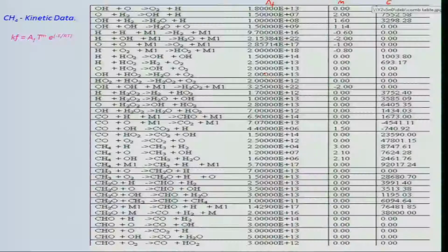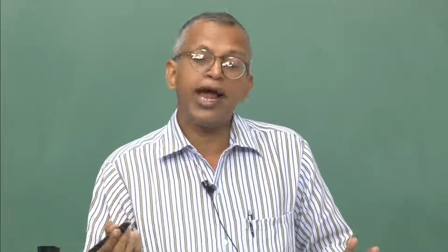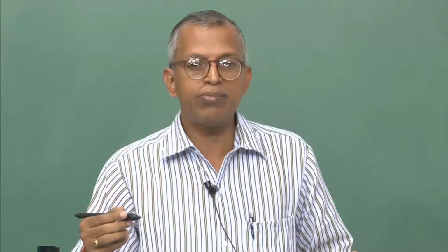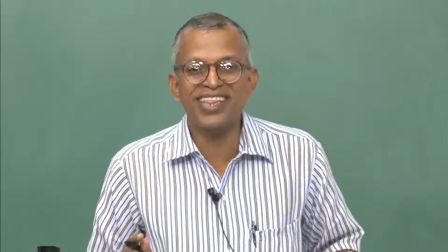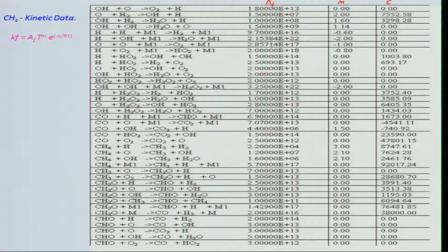So, this has to be solved. The number of species is 14 in this case, and the number of reactions is 40, and backward reactions also have to be considered, which is done from the equilibrium chemistry, which I do not want to discuss further because it will be quite complex. And this is being used in combustion modeling, and this chemistry cannot work for rich mixtures.